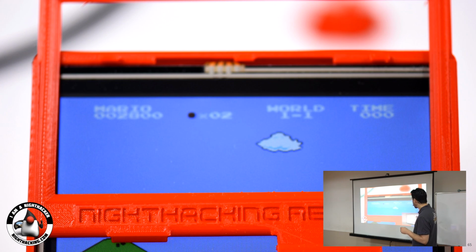And the screen in the whole case is designed so it all slides together nicely. So there's pins on the top and little channels on the side. So you slide it down from the top, and then you just pop it out a little bit and you push it in here. So by having two directions, by going down and then having pins which go the other direction, it locks it in place securely without the need for screws.